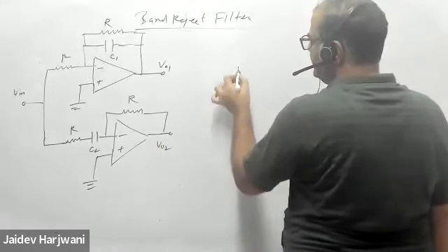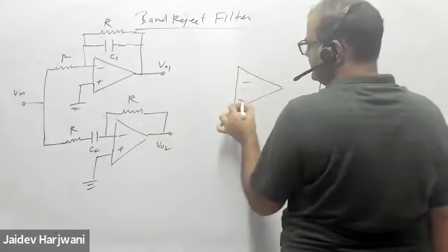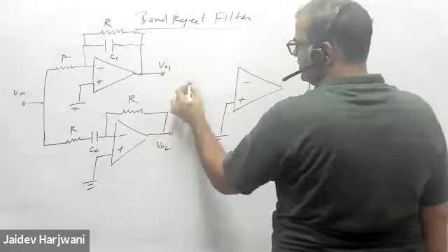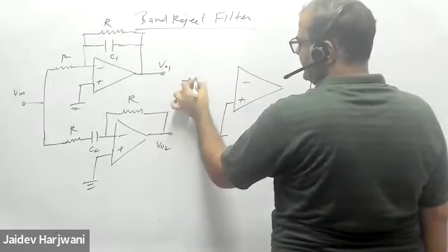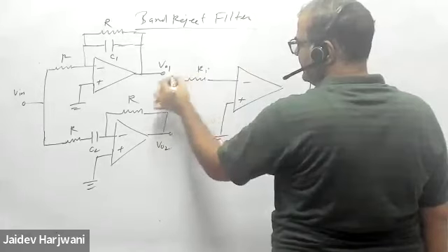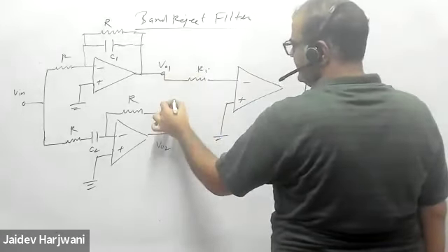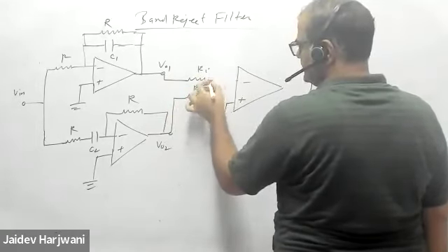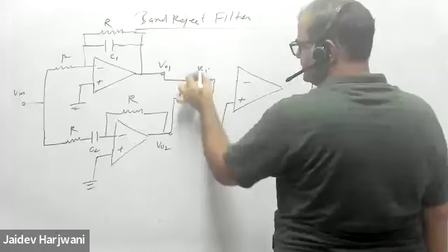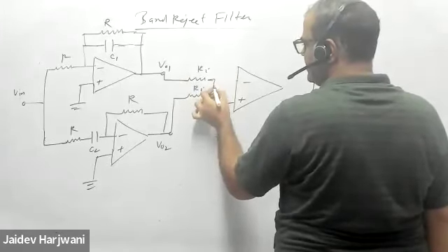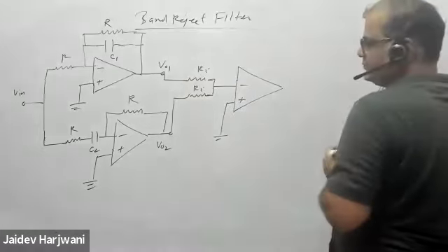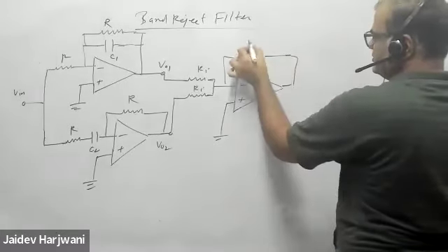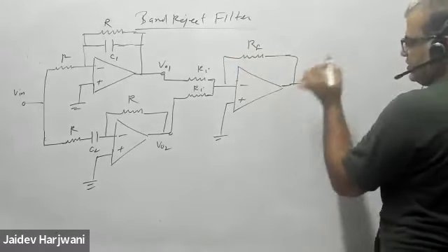Now what happens in the summing amplifier? In a summing amplifier you have an inverting configuration, minus, plus, and this is ground. And here we use this output. So say a signal goes through an RI used here, and from here also an RI, combined in the summing amplifier, and this goes here, and here you have one RF, and this is your final V0.